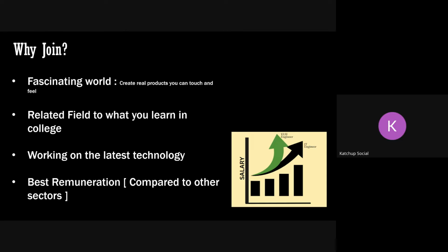So as I said, congestion is not linked to RTL design. Congestion is linked to how wires are connected. So RTL engineers don't have to do anything. Physical design engineers have to fix the congestion.